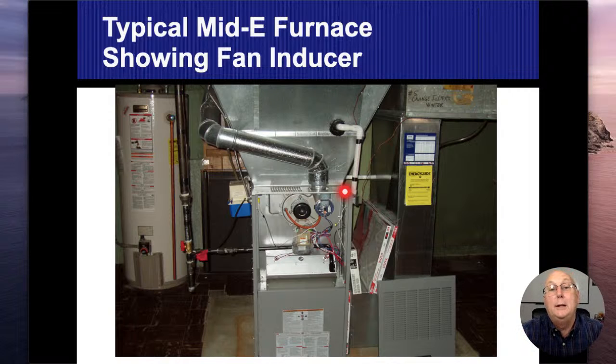This furnace was changed out. They put a new one in there. It was more efficient than the old natural draft furnace that was there. So it does send up less BTUs than what's going up on there. These vent connectors and vents are supposed to be sized to this appliance, not to the old one. All right. So whether or not this is going to continue to work, I can't say. All right. But I am going to be looking for signs of condensation on all of these joints. Any sort of dripping or anything that's going to show where I have any sort of bad drafting, and I'm going to be aggressive with it.